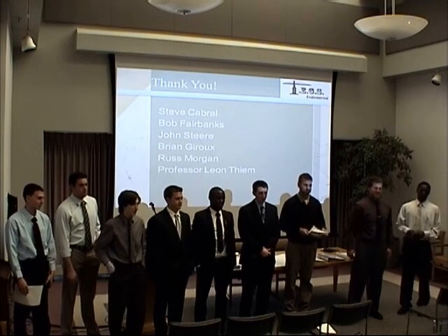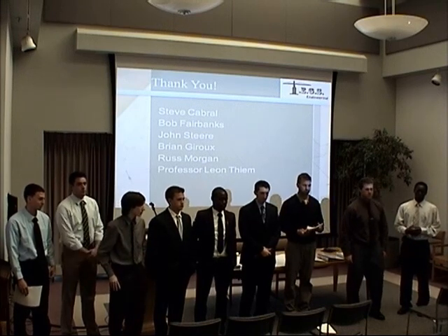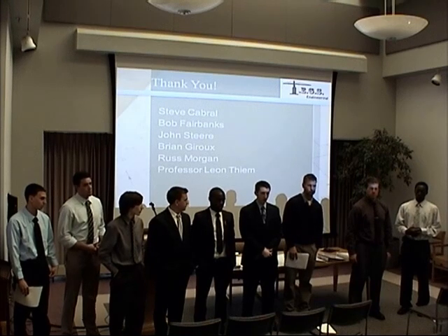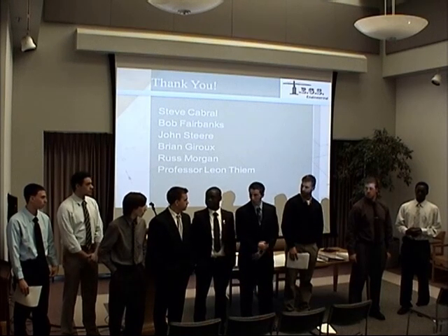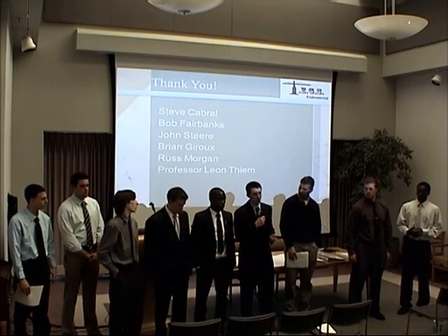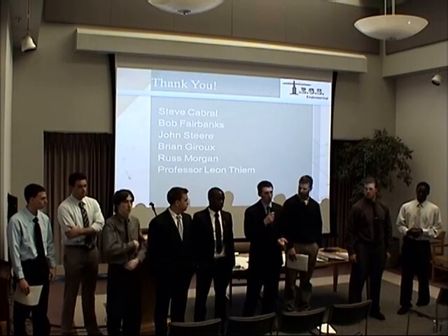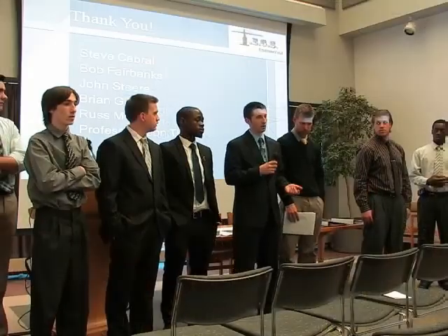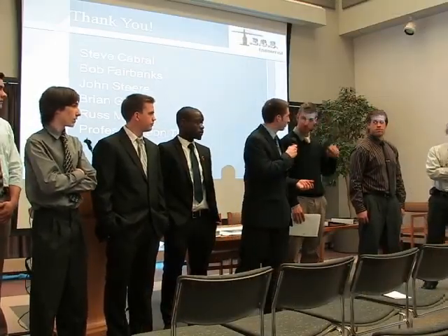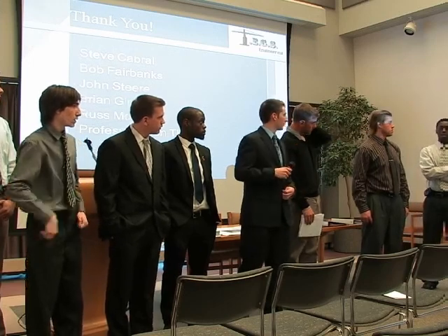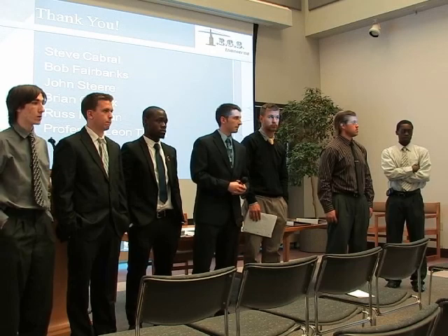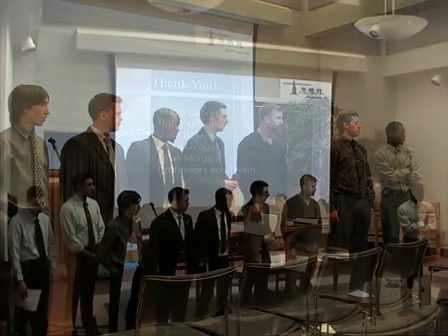What was the 100-year still water elevation? What was the elevation of the first floor of your buildings? Yeah, 22 feet was the level of our first floor elevations. The flood elevation was 21 feet. And what was the still water elevation? Still water was 16 feet.